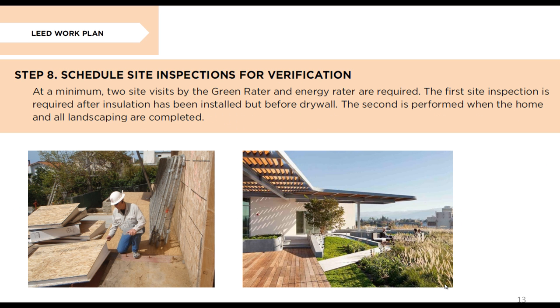Step 8. Schedule site inspections for verification. At a minimum, two site visits by the Green Rater and Energy Rater are required. The first site inspection is required after insulation has been installed but before drywall. The second is performed when the home and all landscaping are completed.